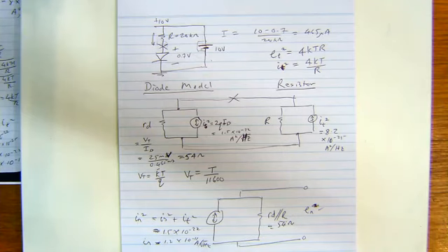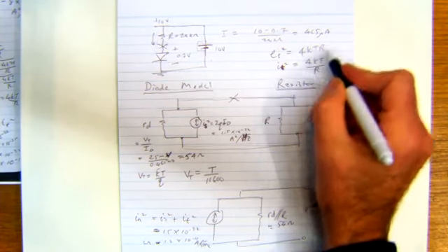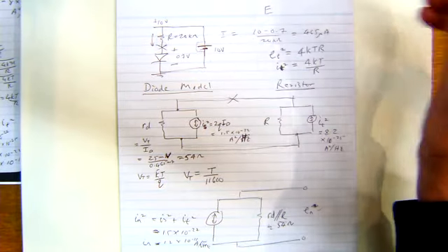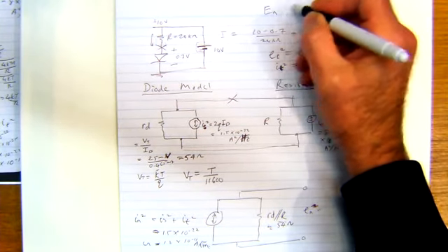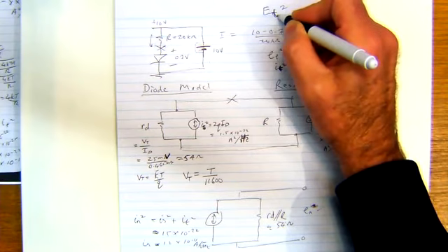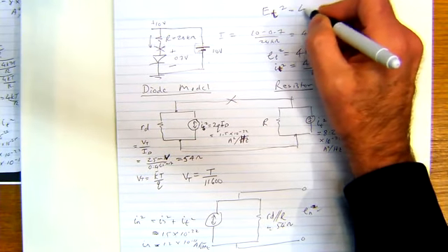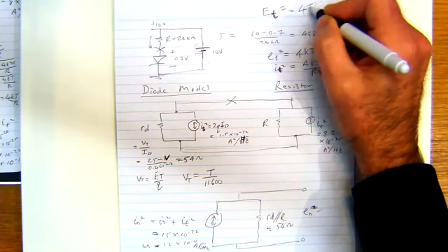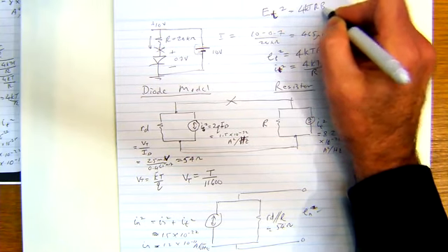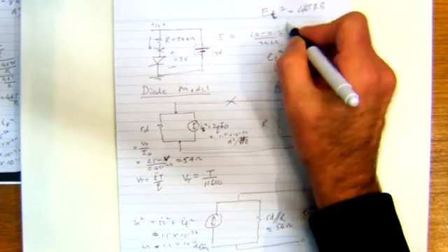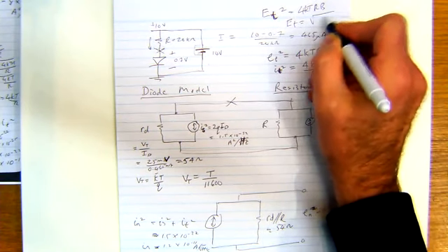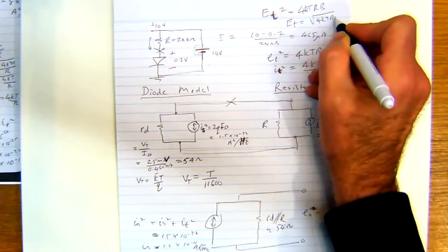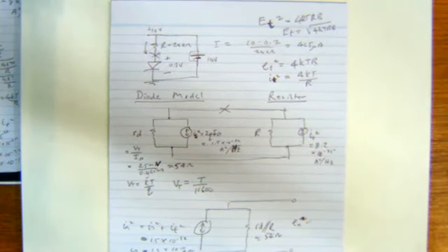So then all we need to do is multiply by the bandwidth. But don't forget, it will have to be the square root of the bandwidth, because ET squared is 4kTRB, so ET is the square root of 4kTRB. Did that fit on the page? Yes, just.